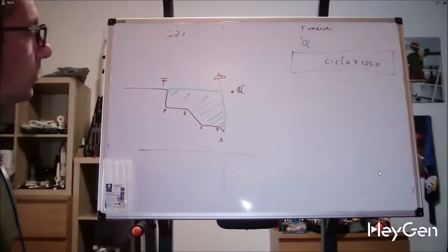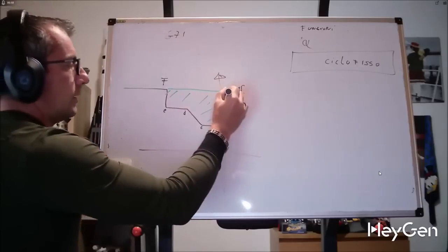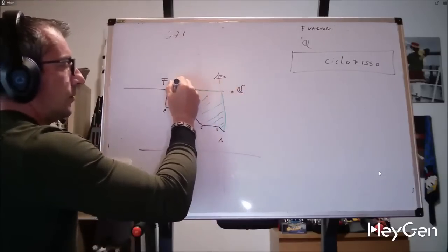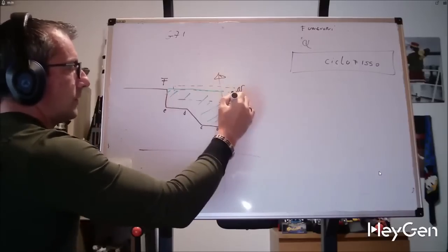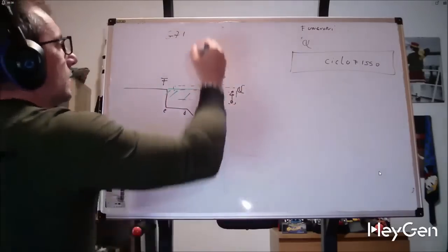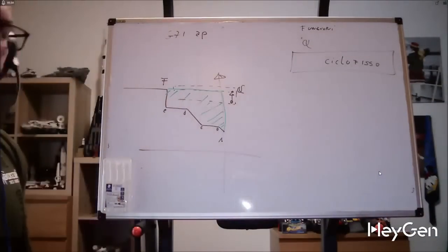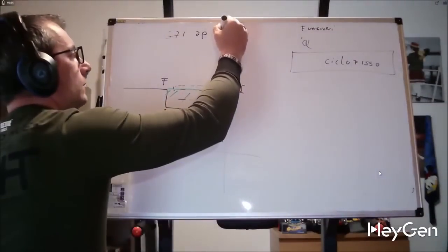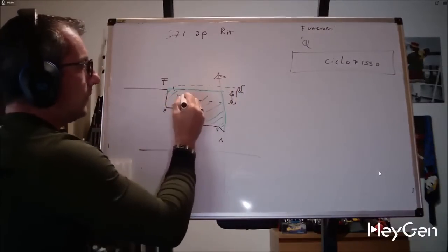Then we should give depth of cut, meaning every time I make a longitudinal pass, I lift up, I come away, and I don't lower, and I start again. This distance, radial depth of cut. So let's call it out, depth of cut, and R for return, meaning how much I retract.